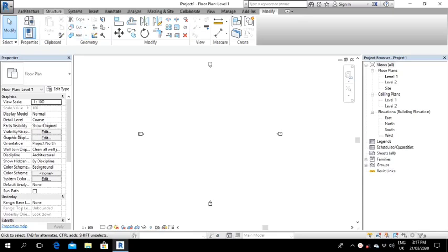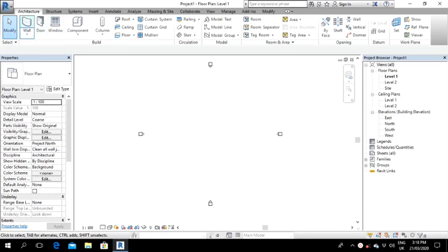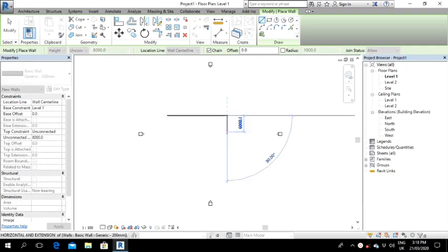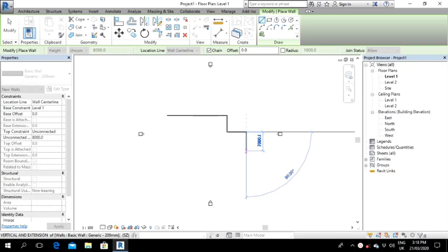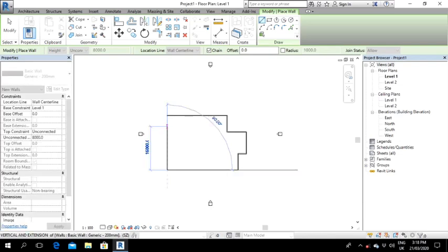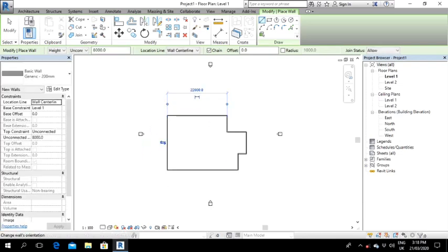In this video, I'm going to show you how to use these basic modify tools on Revit. Now we'll start with align. For instance, let's select a wall, just a simple wall. We'll make a drawing of this nature. We want to demonstrate how align works. Tap escape to escape from the walls.